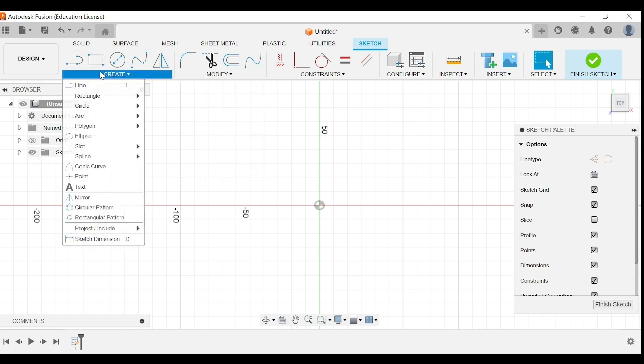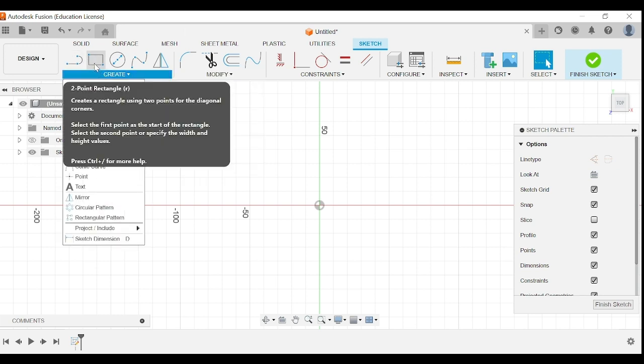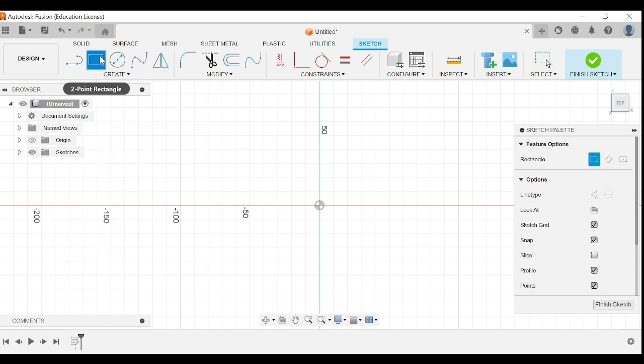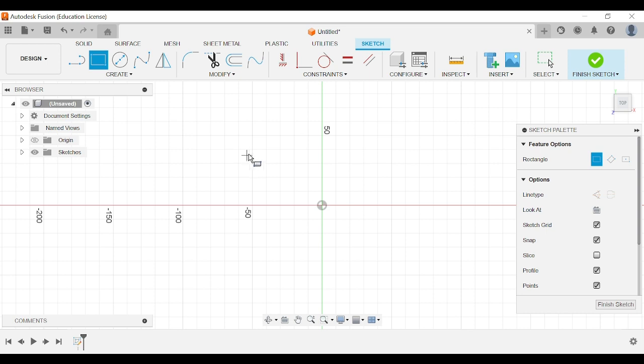For our DICE project, we need to go to the square one, the rectangle. So if we click on the rectangle, you can see it highlights in blue. And what you got is you got this little cross, that's the word, cross. And what you can do is you can put it right in the center right here. You can see when it's in the center, it highlights it in blue. You've got a little rectangle, you know that's in the center. If you're not in the center, it's not like that. So we want it in the center, and we can just drag it out, and you can see we've got dimensions here now.